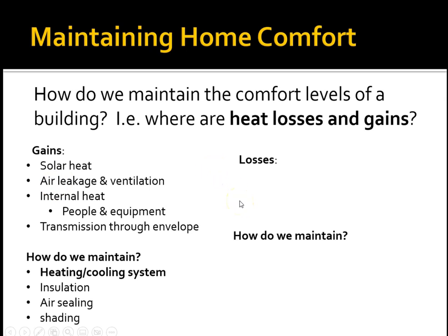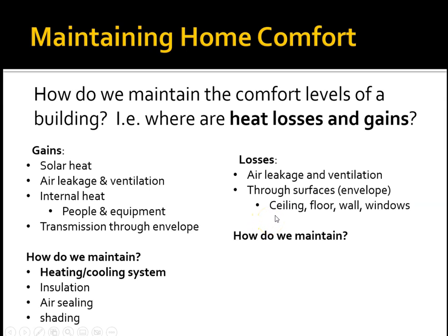So I want you to think about how heat can be lost in a building. Go ahead and press pause and think about that. And really, it's similar, but sort of opposite, right? Just like we can have warm air leaking in the summer, we can have warm air leaking out in the winter, right? And then through ventilation, imagine it's really cold outside and you're bringing in fresh air. That's cold air, right? And when you bring in that cold air, an equivalent amount of warm air goes out of the building, which we'll talk about later. So that can result in heat loss.